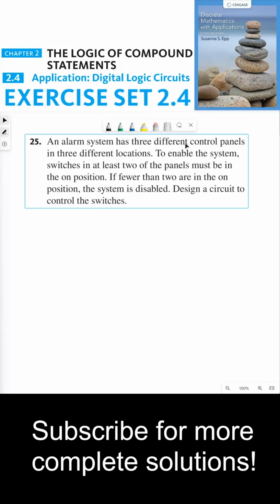An alarm system has 3 different control panels in 3 different locations. To enable the system, switches in at least 2 of the panels must be in the on position. If fewer than 2 are in the on position, the system is disabled. Design a circuit to control the switches.